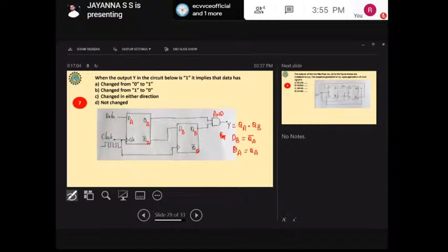First, I am going to write out the table. I am going to take the clock as one input. I am going to consider the data, and two outputs, QA and QB. Let us check QA and QB. Without any clock, think that I initially get 0, 0, for simplicity. Next, for the first clock, think that the data is D1.